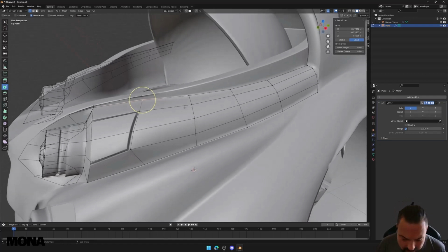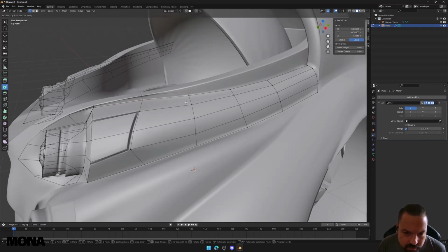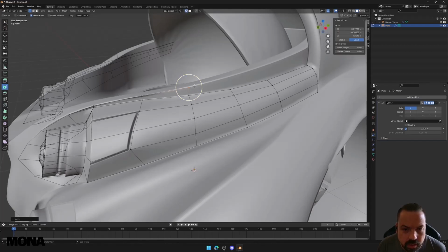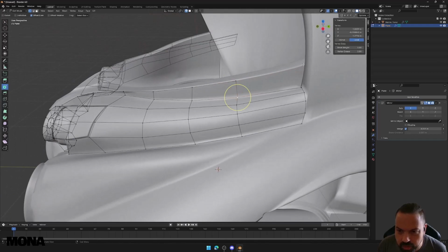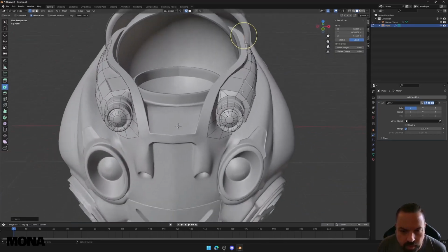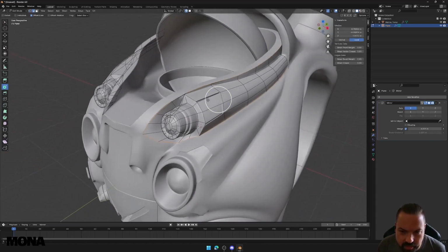Another tool, F, maybe, or just standalone Blender, is if you have a cut like this, and then you just press F, it will put the polygon where it would be as a square, and then I can easily just adjust. Put snap back on. G, so that F, and then sort of just do that, which, as you can see, is pretty quick. Let's get all of that.